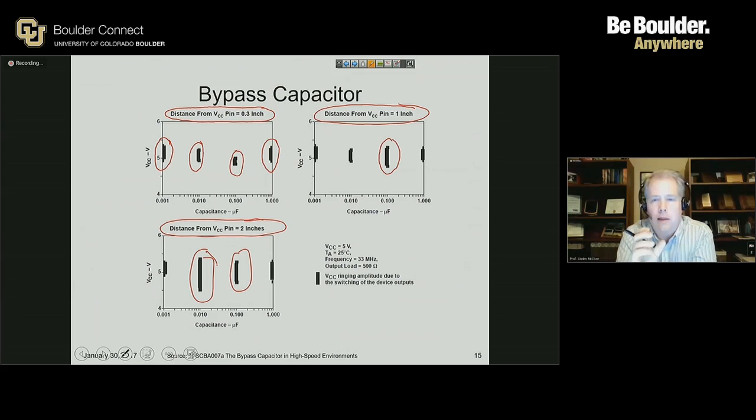Every single integrated circuit that you're going to add onto your board this semester should have a bypass capacitor added to the board as well. The 8051 processor that you have put on for Lab 1 will probably be one of the largest current draws of any chip that you put on. It has a large number of outputs that it switches simultaneously, and therefore the decoupling capacitance that you provide to that chip, the 8051 chip, has to be larger than the decoupling capacitor that's needed for many of the other chips that you put on the board.